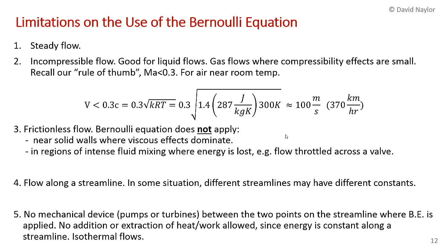The other assumption, and you saw when we performed the integration, we assumed the density was a constant in the integration, so we're assuming incompressible flow. So Bernoulli's equation is great for liquids, but you have to use it with some caution for gas flows. Gas flows where compressibility effects are small, you can use Bernoulli's equation. Remember from, I think it was chapter 1, we talked about the idea of compressibility effects and this idea of the Mach number.